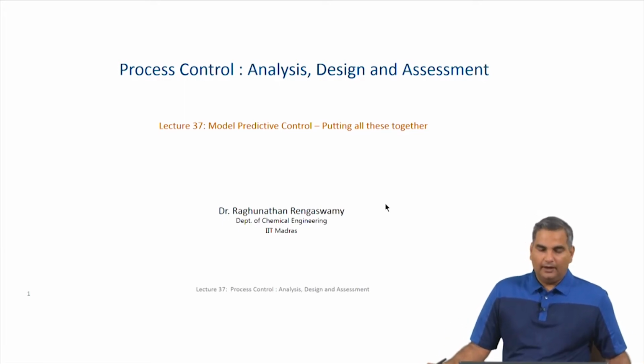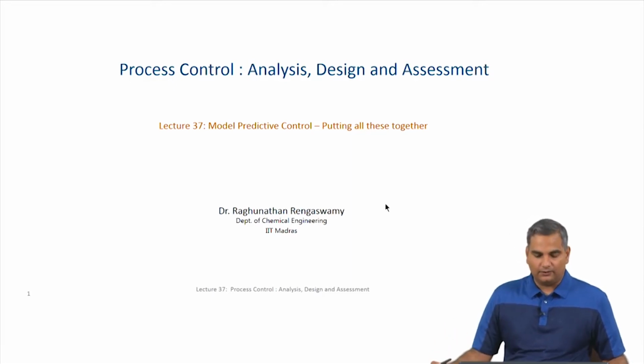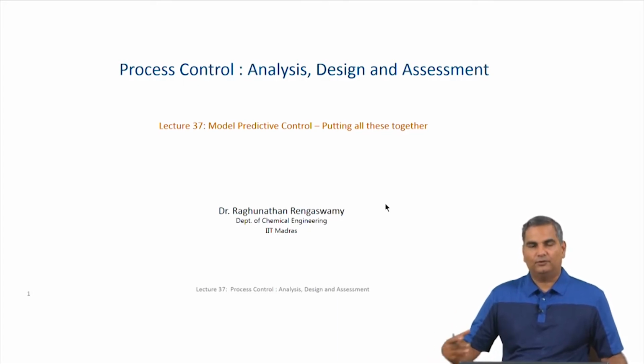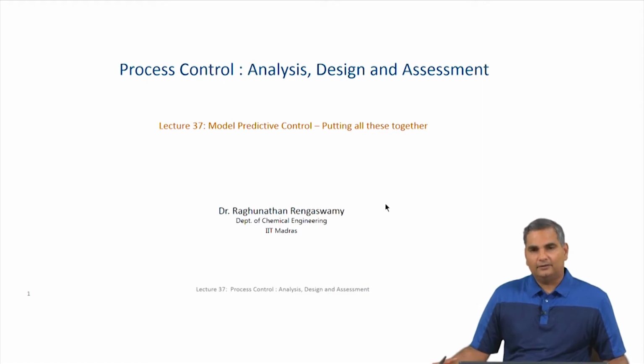And the beauty of this model predictive control formulation is that since we have an optimization formulation and not an analytical expression for the control law, any optimizer can be used to solve this problem. So, if you find a more efficient optimizer, you can simply use this formulation with that optimizer. So, the accent in terms of the model predictive control material is more on the concepts of formulation and how do we formulate this problem, rather than the solution, which is a standard optimization solution that you can use.